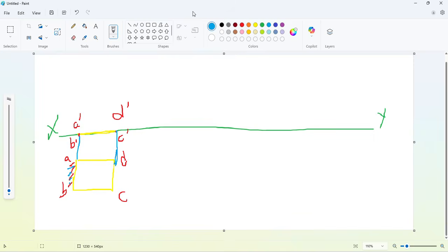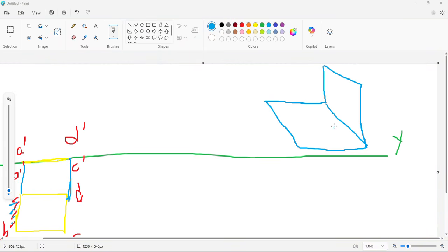with the HP. So this is our first quadrant, and as per the question, we have to show our rectangular surface making an angle of 60 degree with the HP. For that purpose, while resting on this edge AB, so this is our resting edge AB, we have to rotate this in this direction so that the surface makes an angle of 60 degree with the HP.